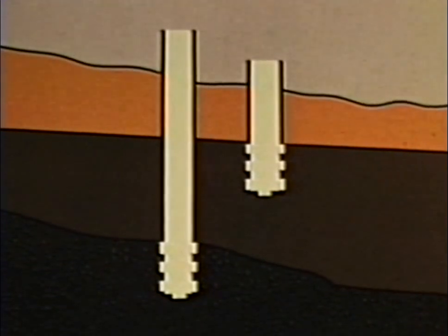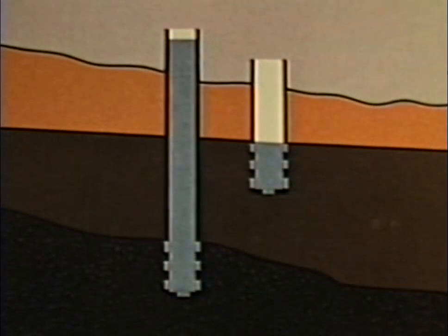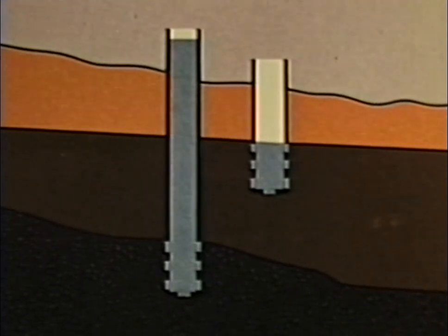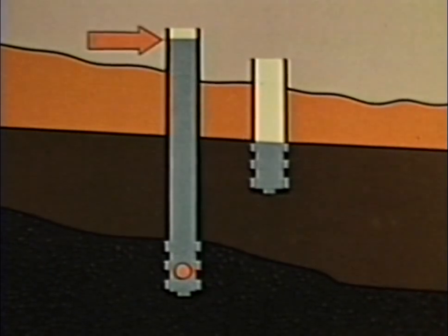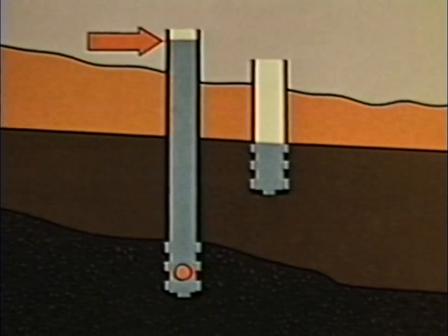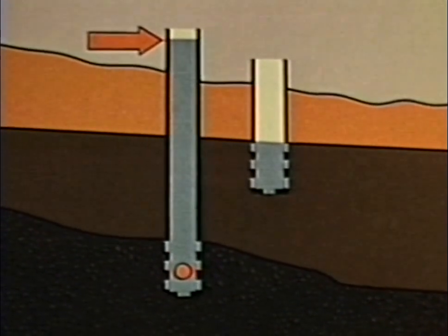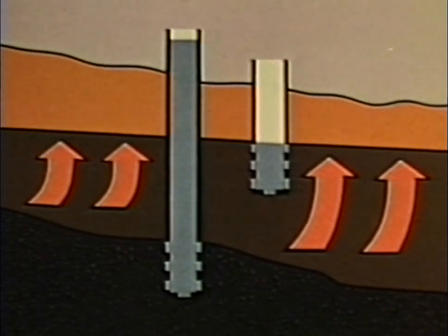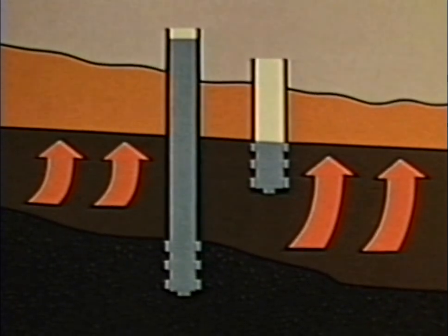To determine whether groundwater moves upward or downward near the water table zone, 2 or more wells are needed. The water level in the deeper well rises to a level much above that of the water table. The hydraulic energy of the deeper groundwater is highest. The direction of groundwater flow is upward. This is a discharge area. Water flows from zones of higher energy to zones of lower energy.